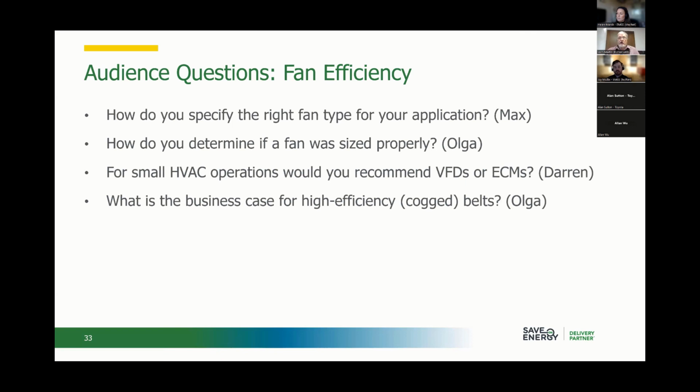Or if they started off lower than that, which may be the case for smaller equipment, the smaller the equipment, the more inefficiency you have with V belt drives. Down at a 1 horse motor, I think the efficiency of one of those belts is probably not much better than 75%, or maybe better than that. I'm not sure. It's not that easy a thing to measure, frankly.